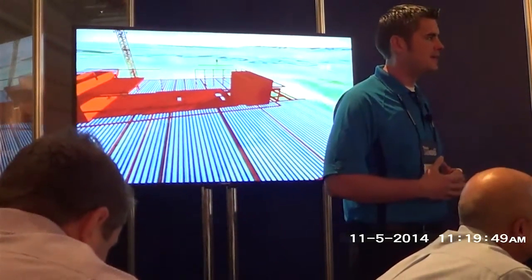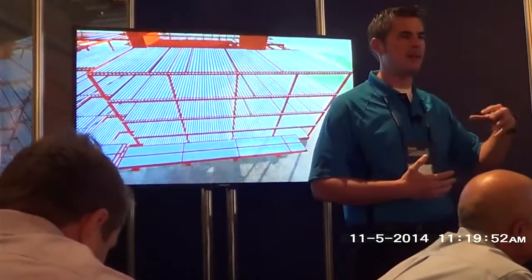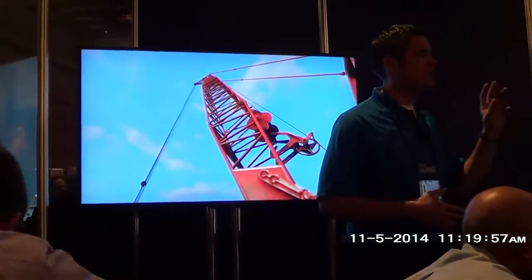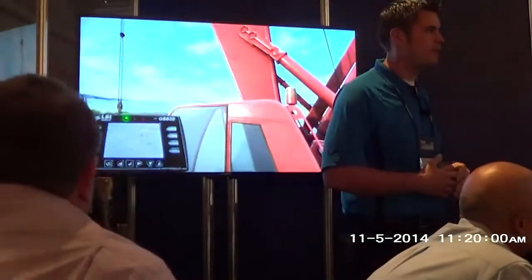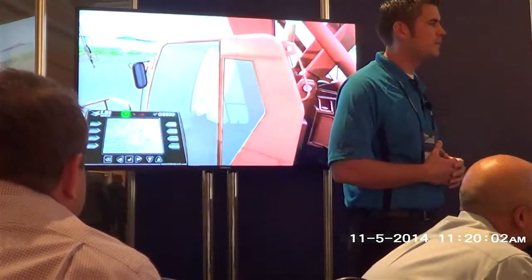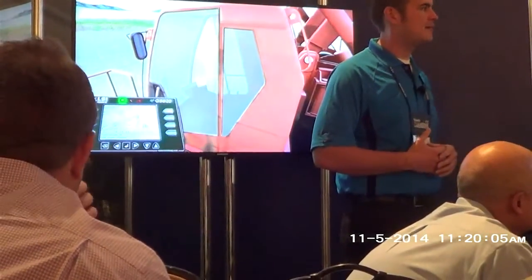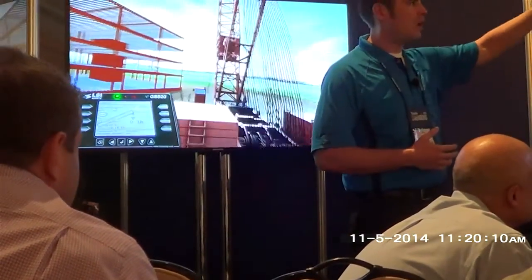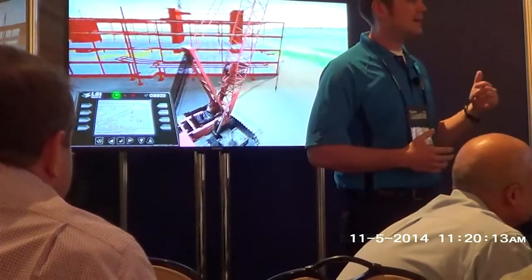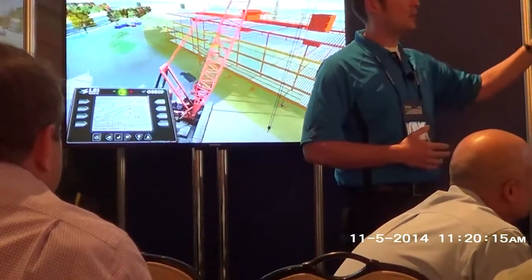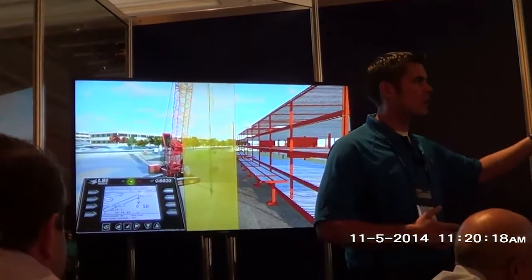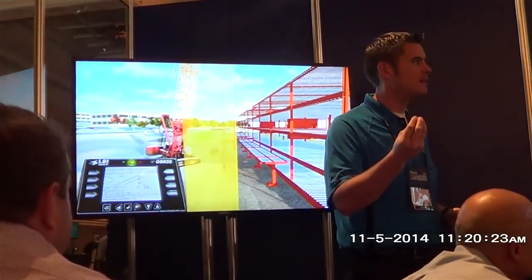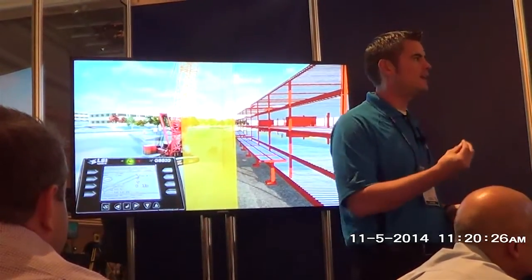So now our beam is getting set, and while that's happening, there's another crane on the other side of the building. Now this is a crawler crane. Crawler cranes are very large, very heavy pieces of equipment, so there are some safety implications with that. To address those safety implications, we have this LSI technology that's mounted inside the crane cab and also on the boom. This technology lets the operator know exactly where his boom is at any given time. So the slope, the swing, the slew, and even the tension that he has on his hook at any moment. It's also making him aware of overhead obstructions.